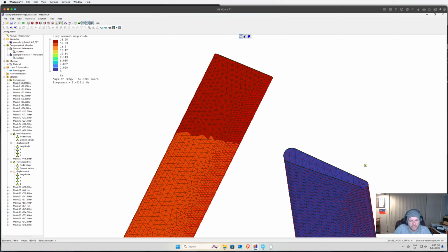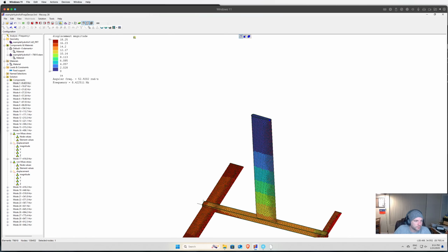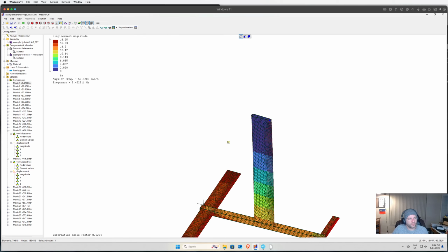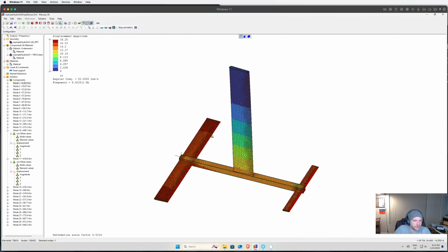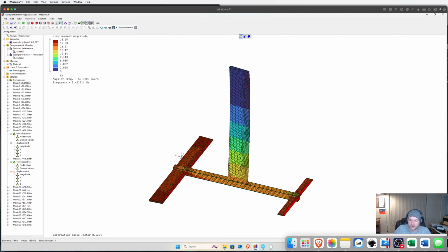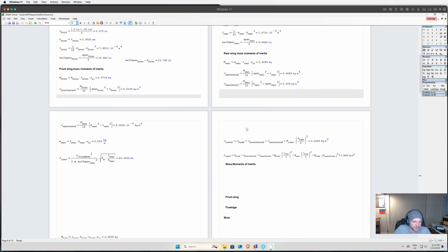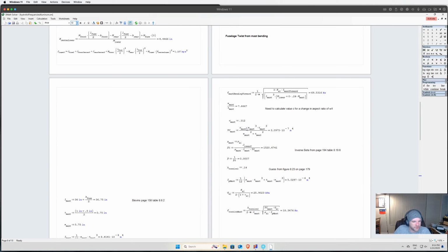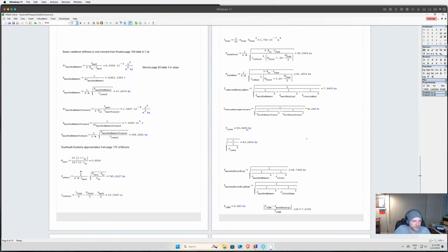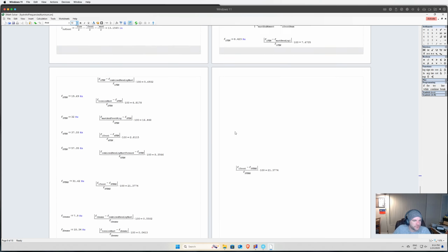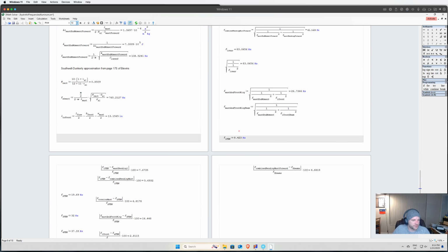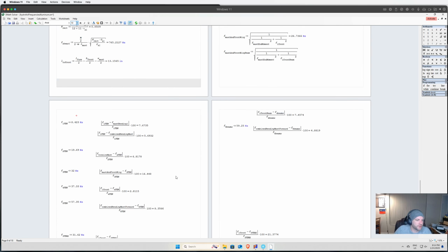It's an inch across. It's half an inch in the back, and so the beam I used was just a rectangular beam to approximate the mode of this. But so I did this FEM model, or finite element model, and I got this bending mode. You can see here. So that's the first mode I hit, and by hand, this is the easiest one to calculate. I did have to play with some of the inputs a bit. Anytime you do vibration, you do end up needing combined modes, and it's best to not have to do any kind of fudge factors. I don't like fudge factors. It means you don't really know what's going on.